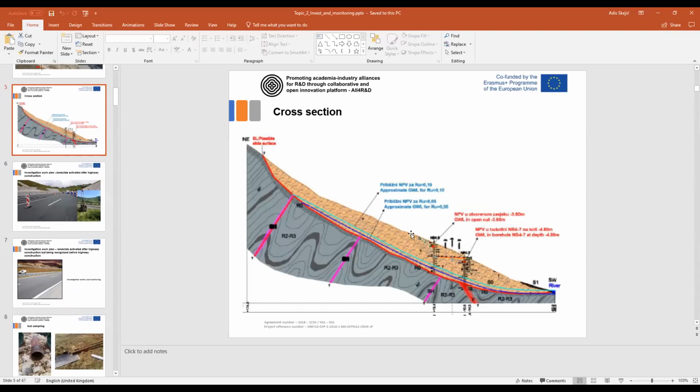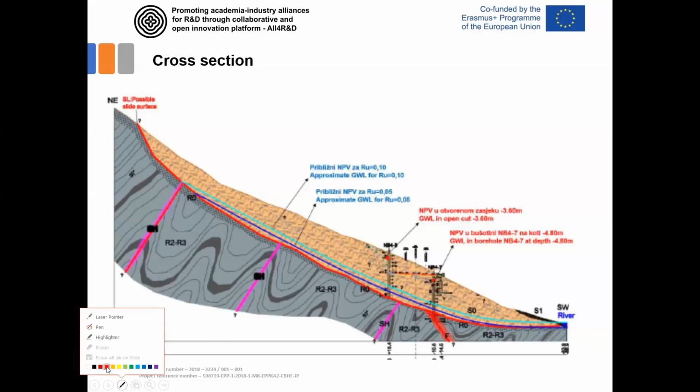Well, in the landslide area, the depth of the borehole always has to reach the stable area. So if we drill a hole here and just stop the borehole before we reach this line of the, let's say, good material, rock-like material, then this borehole is really not useful.